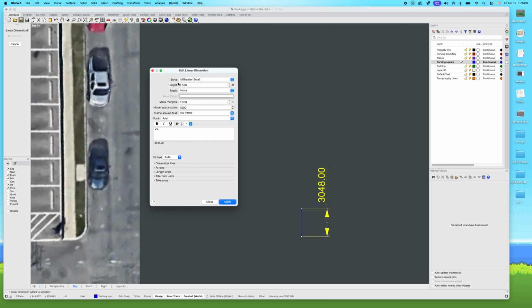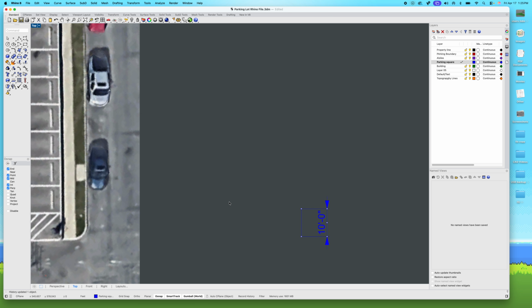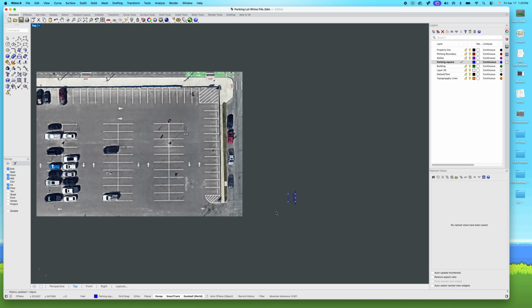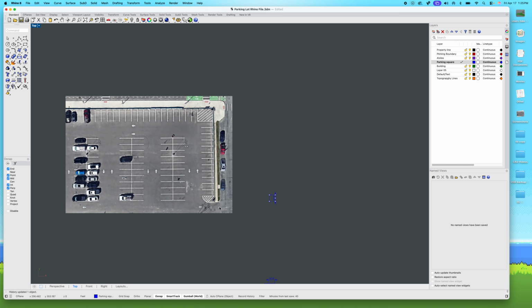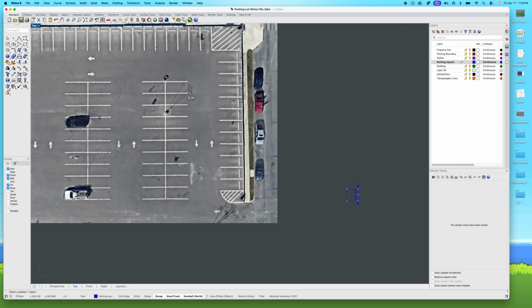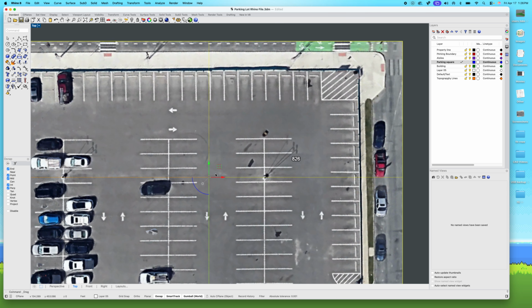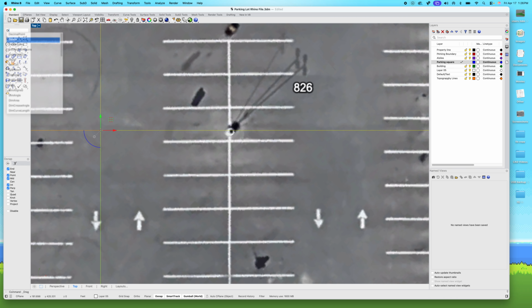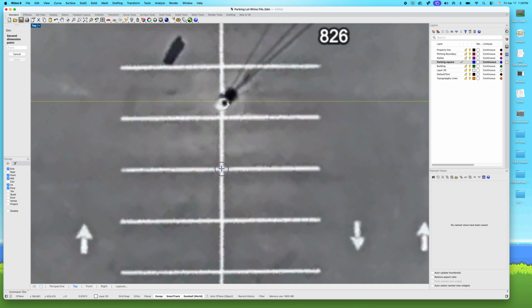There we go. So if you do want to change it, make sure you go to length units. Instead of millimeters, go to feet and inches, and voila. Now, I was pretty sure I set my global settings to that, but I guess not. In your case, somebody might have done that on your computer already, or you might have done that yourself already as well. Now this is looking pretty sweet because I can assume that essentially all of these are 10, and I can use DIM to get other dimensions as well.